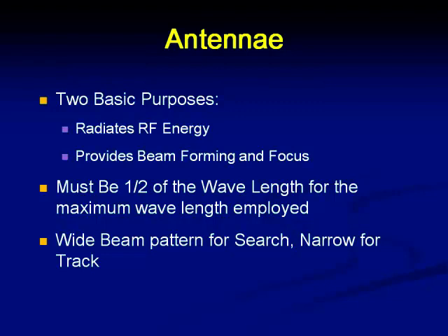And for normal operations, as we know from antenna theory, the length of the antenna must be proportional to half the wavelength of operation. But this gives a very wide beam. If a wide beam is required, it is okay to go with these λ/2 dipoles. But we know very well that for tracking applications we need very narrow beams. The narrow beam can be obtained only with large sized antennas like parabolic antennas.